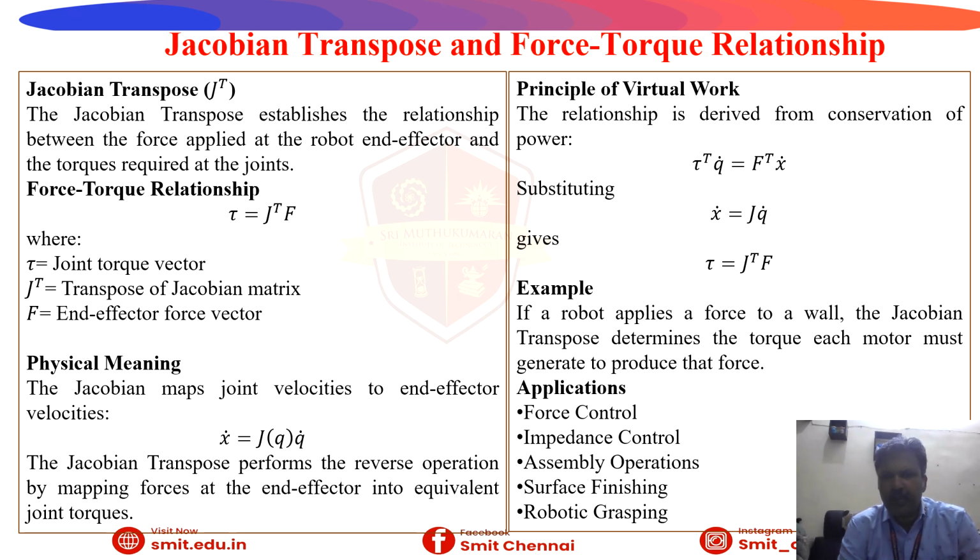If a robot applies a force to the wall, the Jacobian transpose determines the torque each motor must generate to produce that force. Applications: force control, impedance control, assembly operations, then surface finishing and robotic grasping.